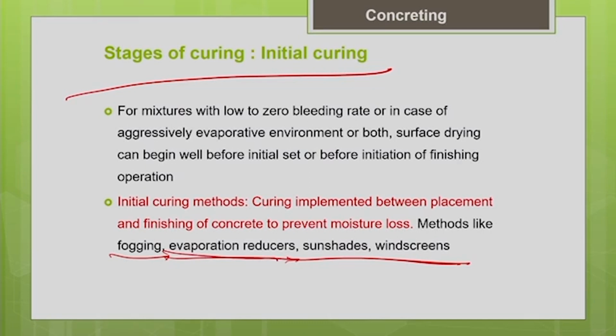These are basically some chemicals, water based chemicals, which are sprayed on the surface of the concrete. When these chemicals are sprayed on the surface of the concrete, they form a kind of oil film on the surface of the concrete and reduce the rate of evaporation of water from the concrete surface.